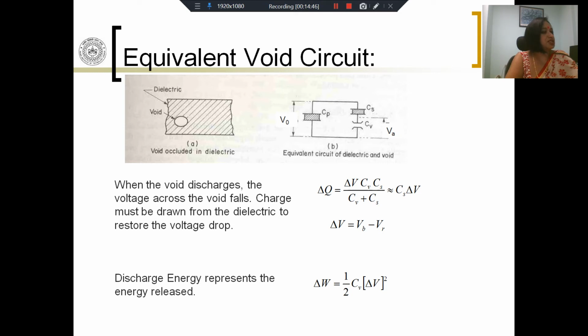It is released into the surroundings in many forms. How do you know that PD happens? For example, when corona happens, how do you know that corona is happening? You can see it by the glow. So therefore, light energy is emanated. Light energy will also emanate when you have PD inside a solid, only you may not be able to see it because you do not have visual access to inside the solid material. There might be light. Corona can also be heard.